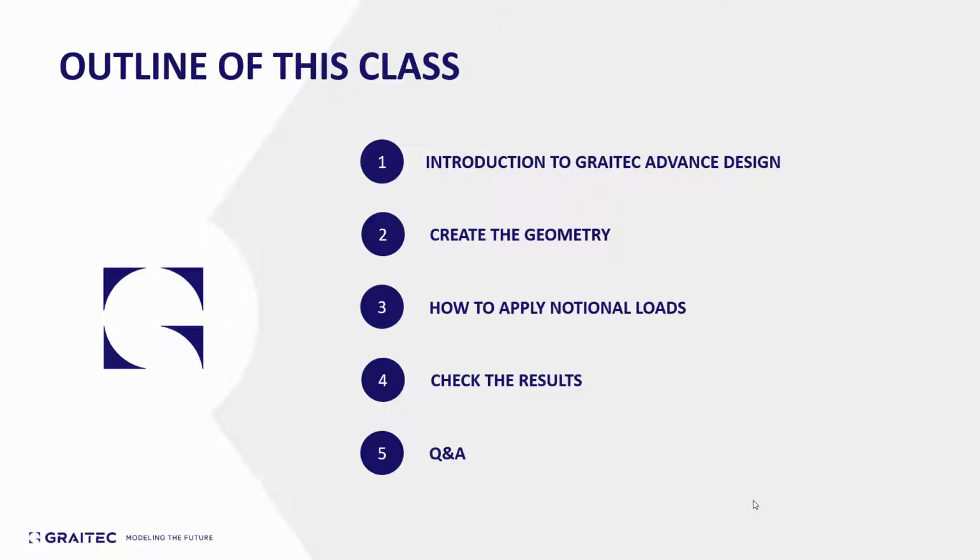Then I'm going to show you how you can apply notional loads in Advanced Design, which are required for some specific structures, steel structures, etc., from different standards for North America. Notional loads include the lateral sway of the structure in your internal forces and design.